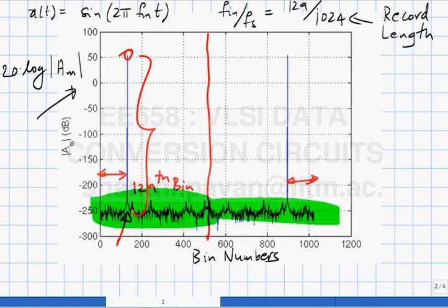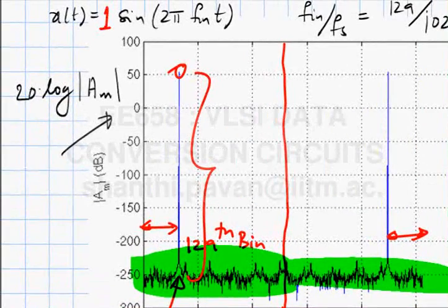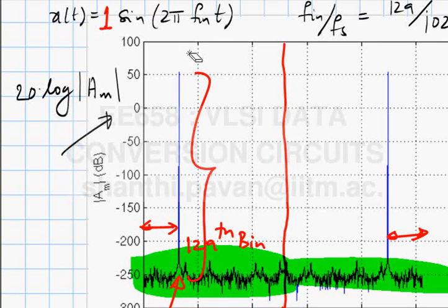So I think the best way to learn all this is to simply do it, and this takes 2 minutes on MATLAB. Even though I put an amplitude of 1, you would expect 1 here, if you expand it as a Fourier series, but it turns out that there are normalizing factors in computing the FFT. And in most cases, you know the amplitude that you put in.